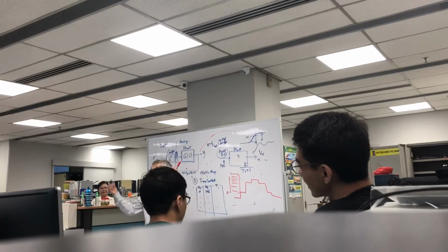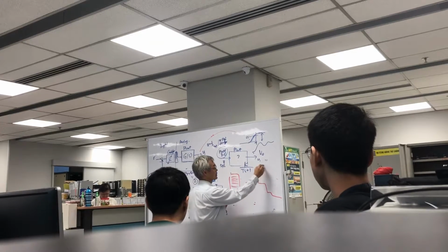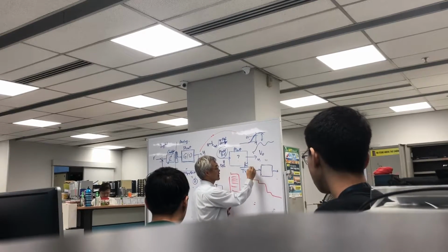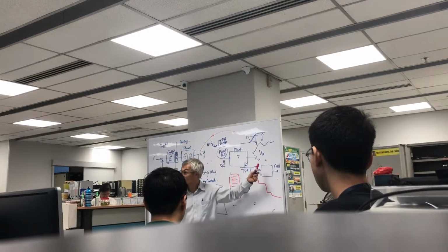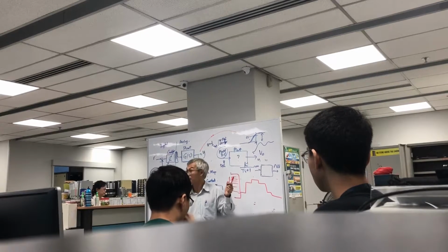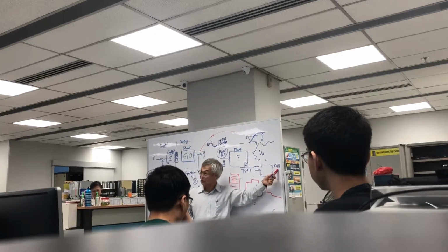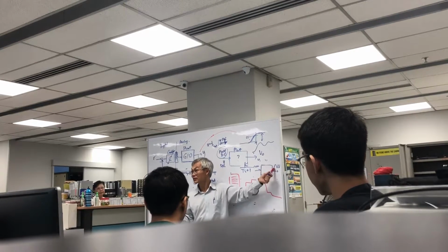So in theory, what is the frequency response? How do you work out the frequency response? You send in a sine wave, you look at the sine wave output. You make sure that the amplitude is small enough so that this also is a sine wave. Linearity assumption.